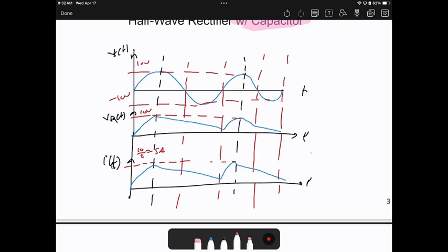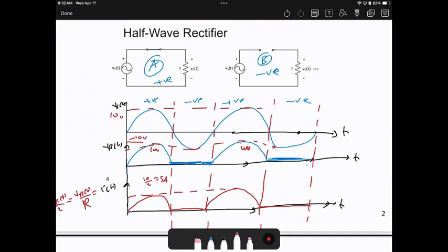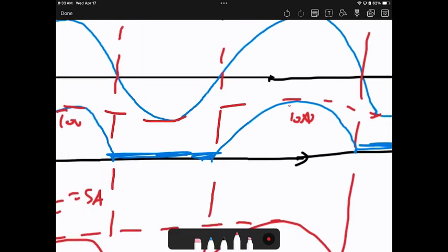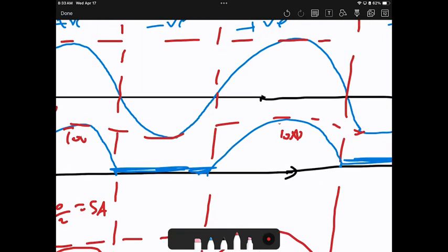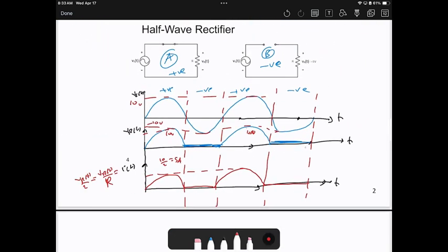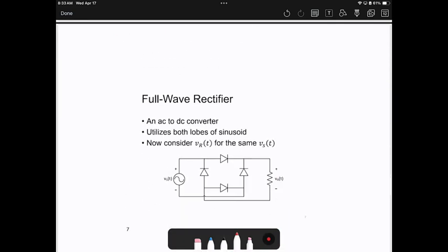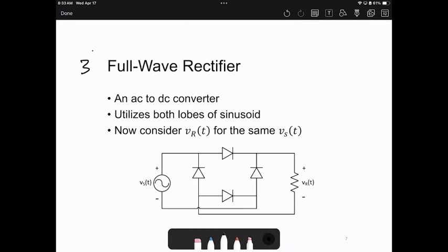So the challenge that we have in the rectifier, which is this part, is that the negative part will be 0. Okay, this is something that we don't like. Is there a way to use this part, but not make it 0? And we don't want to cause a lot of losses because this will be 0. Yes, by trying to find the absolute value of the waveform, right? So by finding the absolute value, which is something that we create, this is the third application, which is the full wave rectifier.